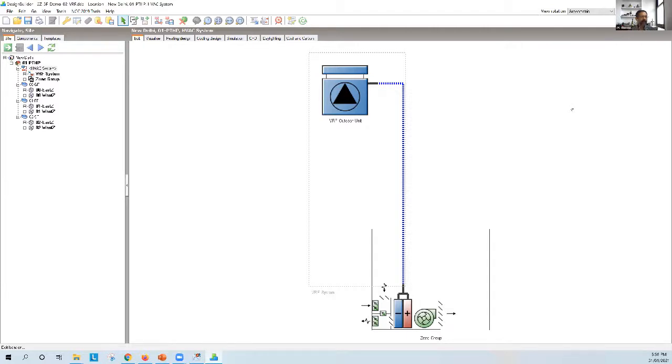However, they are more efficient than normal split systems because typically you have more than one compressor, and one of the compressors will be an inverter compressor. So for the first 50% of capacity, the inverter compressor will have some variable speed potential, and therefore it will be a bit more efficient in that regard. Of course, that doesn't work unless you've got at least 2 compressors in there, and one of them is a variable speed compressor, inverter compressor as they call them. So for the smallest designs, VRFs and splits are pretty close to each other, right?